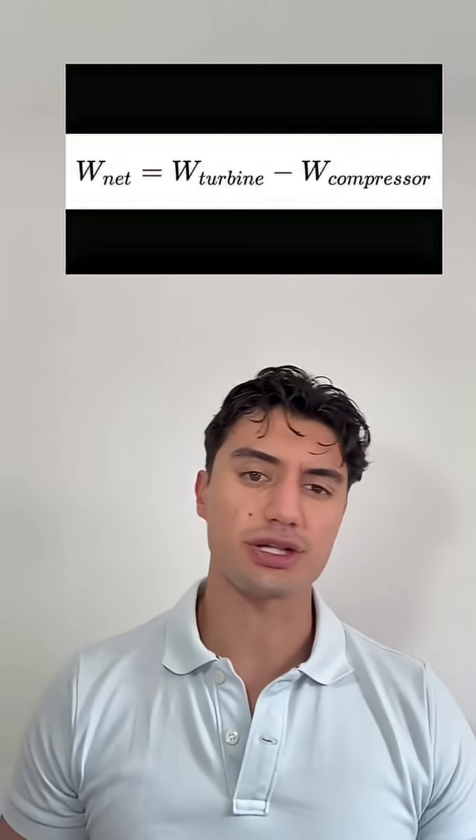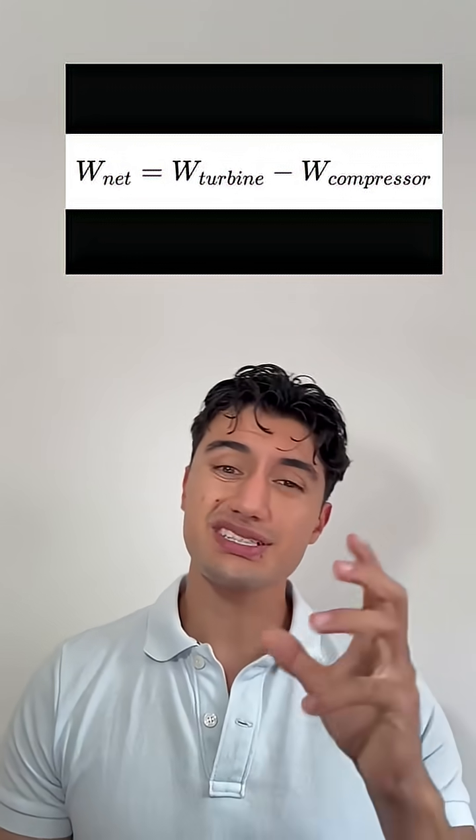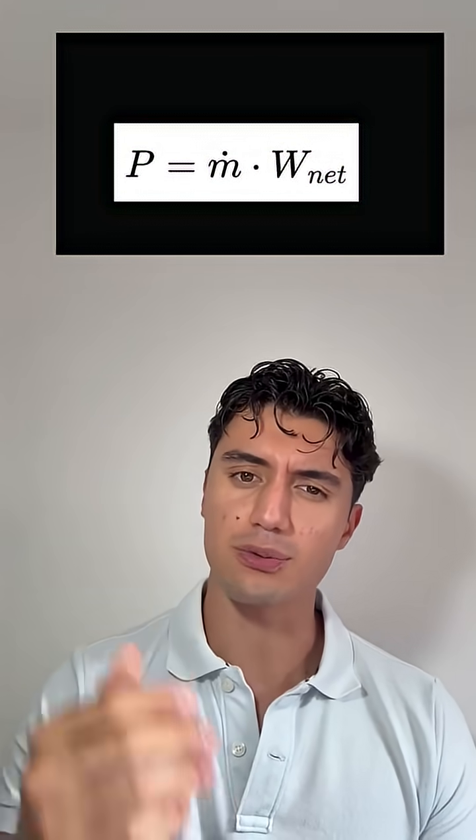Now the net work can be calculated with this third equation, which means subtracting the compressor work from the turbine work. This shows us why the turbine must produce more energy than the compressor consumes. Finally, the total power output of an engine depends on this fourth equation, which means it depends on the mass flow of air through the engine multiplied by the work.